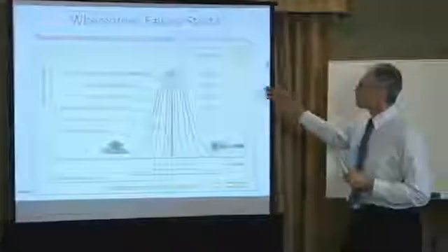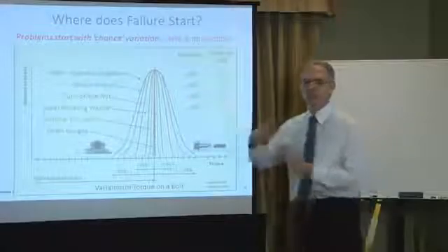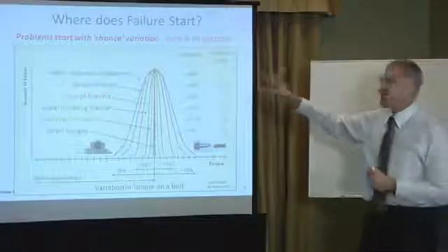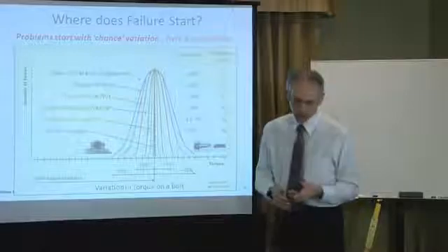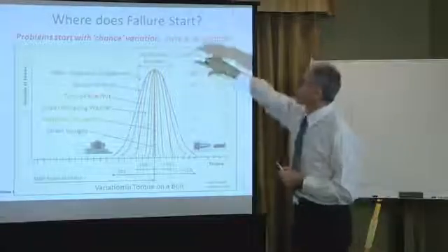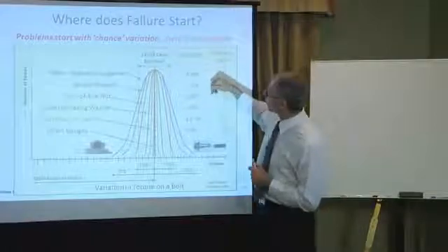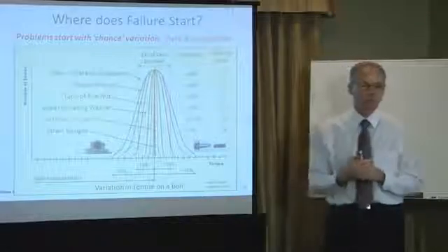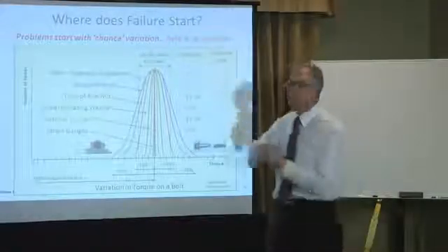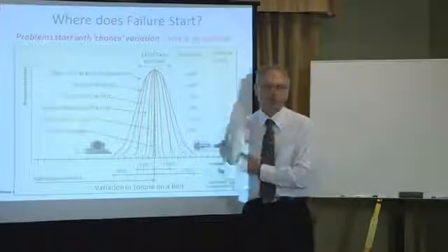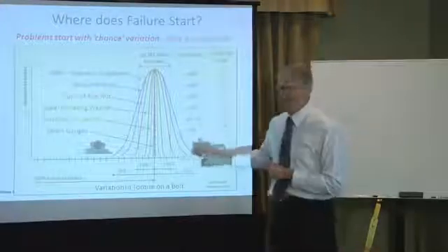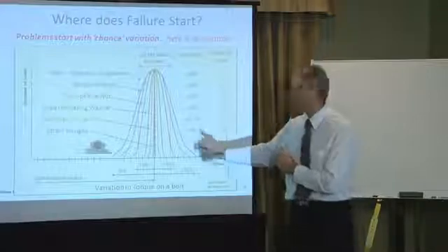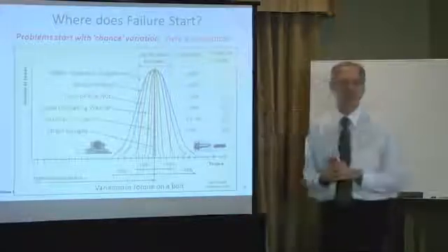The whole point is that the process I choose delivers the distribution of outcomes of that process. Once I make the choice, that is it. That's what will happen. Now, what tricks us is the standard deviation. With muscular feel, this deviation is about plus or minus 12%, one standard deviation. So most of the time, using muscular feel will be okay. It will get away with it most of the time. But every now and again, we're going to get broken fasteners and loose fasteners, because here it's over-tightened and here it's under-tightened. And that's the result of choosing that process.